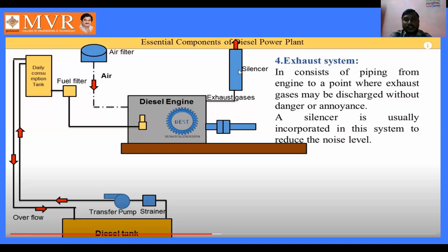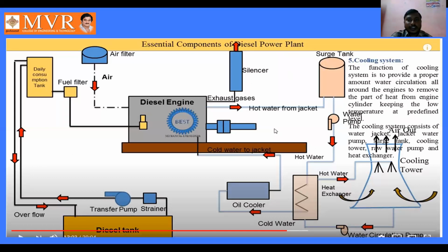This is what about the exhaust system. And coming to the next one, we are studying about the cooling system. See here, from the diesel tank, by using this strainer and this transfer pump, we are going to pump the diesel into the diesel consumption tank.